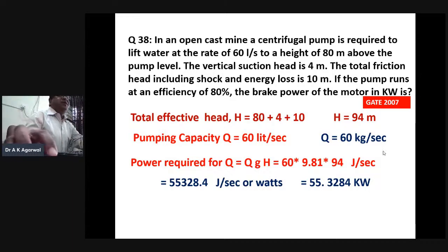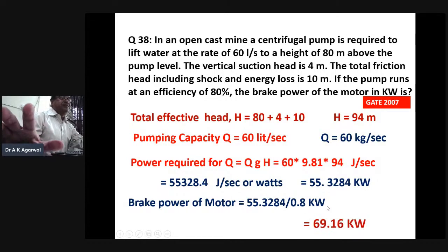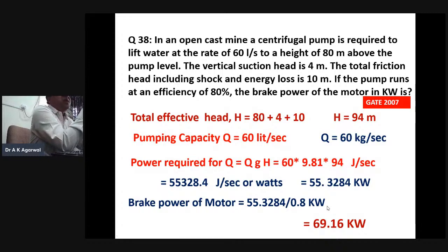But the efficiency of the pump is only 80%. So brake power of motor is 55.328 divided by 0.8, which is equal to 69.16 kilowatt. So a 69 kilowatt motor is required to deal with this pumping capacity.